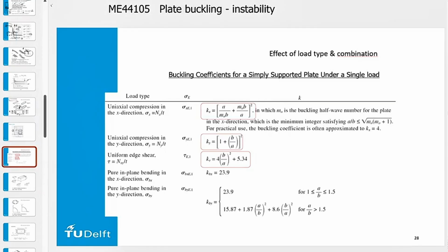Okay, so if we take into account the different limits, then we have here the K factor is 1 for values where the length is higher than the width, and if that is smaller, then we take into account this effect and we square it. And for shear, basically we have the same effect with some correction for a factor for length and width, because there the effect does make a difference, and the standard value as well.